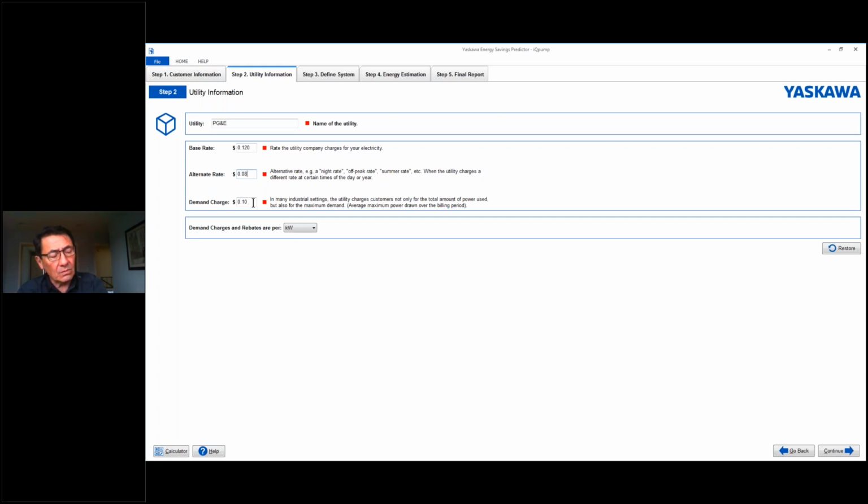The soft start would not limit the inrush current significantly on this application in Guyana, and we had to go to a drive, even though once up to speed, they didn't vary the speed. So they invested heavily in a drive, specifically to avoid the peak power demand charge, and the drive effectively ramped the pump motor to speed without exceeding full load amperage, in other words, running amps.